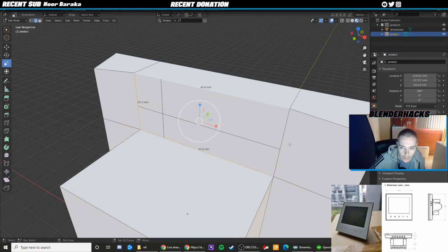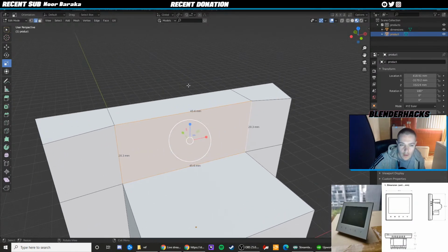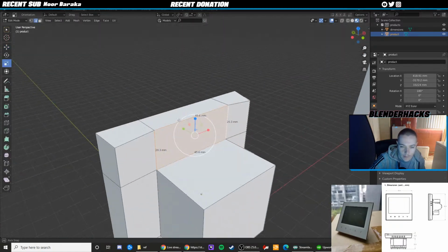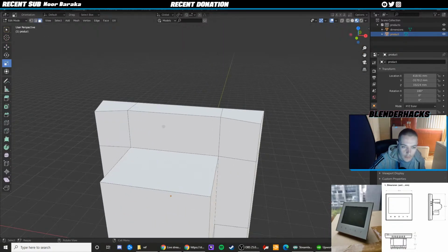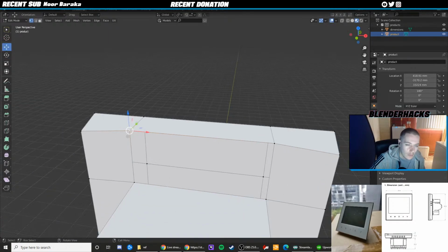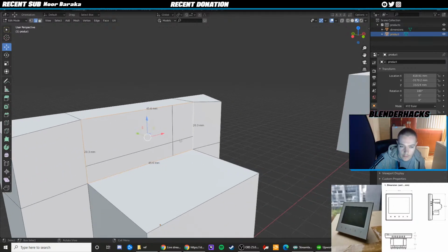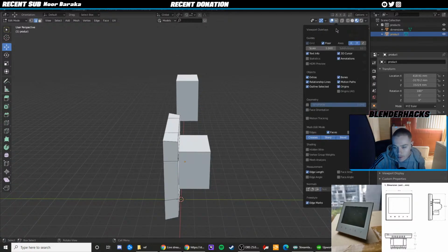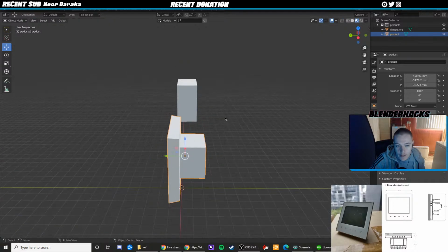It's a good tool to use. F on the keyboard stands for fill, as you fill in any gaps that there are. So just make sure, let's say this face here, you can go this face and press F, but sometimes depending on how complex your model is, this can cause problems. So instead you want to edge select all the faces needed to add a fill, F for fill, press F on the keyboard and fill in the gaps right there. We're going to go into this tab here and turn off our edge length measurement now. We don't need that anymore.